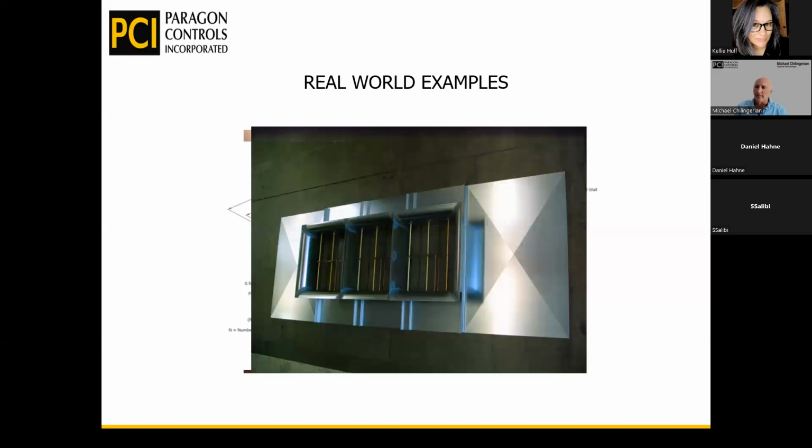Here's a similar one, similar idea. This was on an indoor unit though, and we actually blanked off a large section of the outside air damper so that we get the velocities correct and measure airflow nicely. So something that was factory fabricated, came out as a system, and they just put it together.